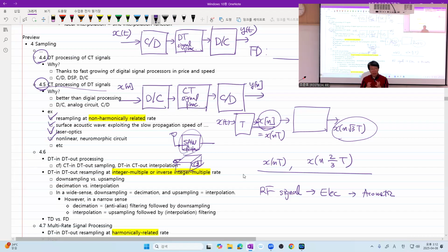And I used RF splitters and combiners. And if you remember correctly, 1 microsecond in free space corresponds to a propagation length of 300 meters. So a 100-meter cable, because the speed of light is faster than the speed of propagation through the cable, may correspond to around 300 meters of free space, which may induce a multipath difference of 1 microsecond.